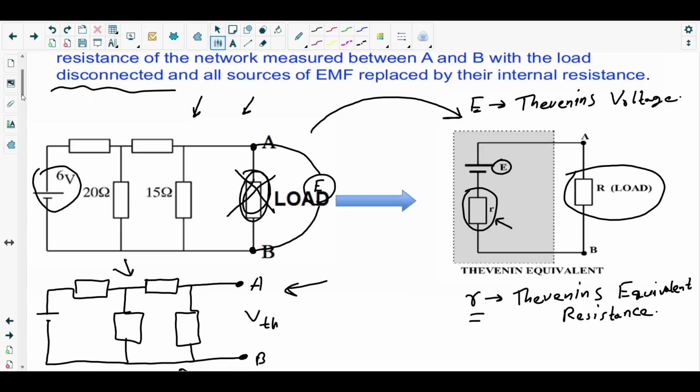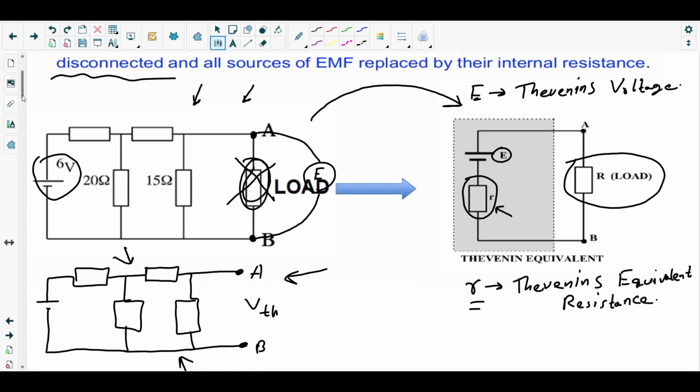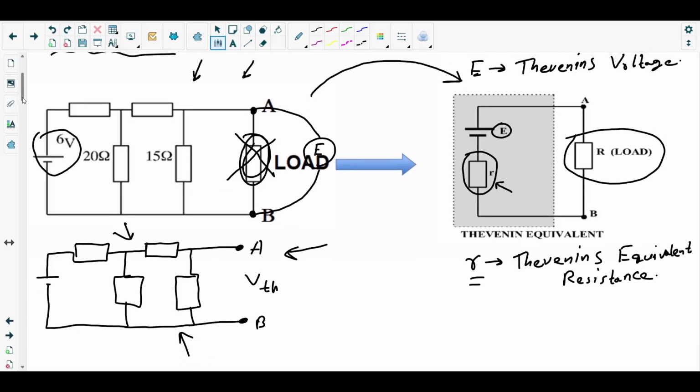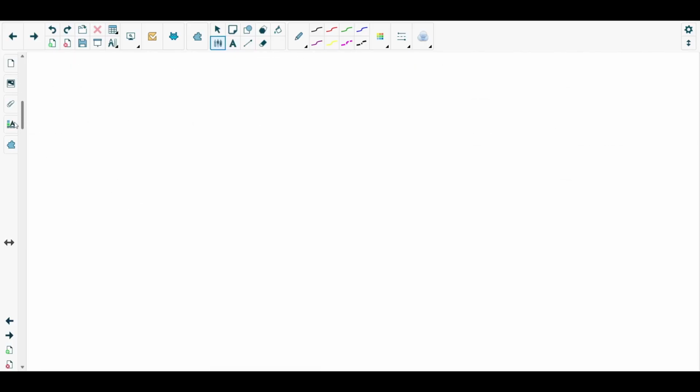So in this Thevenin's equivalent circuit, if you short circuit the load resistor, short circuit means instead of the component, the load resistor is a component, you put a non-resistive wire there, just a wire there without any component. So that would be just a complete circuit with no load resistor in the Thevenin's equivalent circuit.